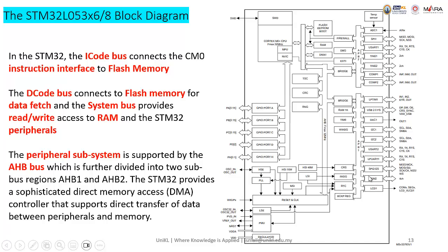for timer 2. But when we use timer 21, for example, we need to know the clock of the APB2, because timers 21 and 22 here are connected to APB2 and not to APB1. That is the most important thing that we need to understand. Others, just forget it, right?